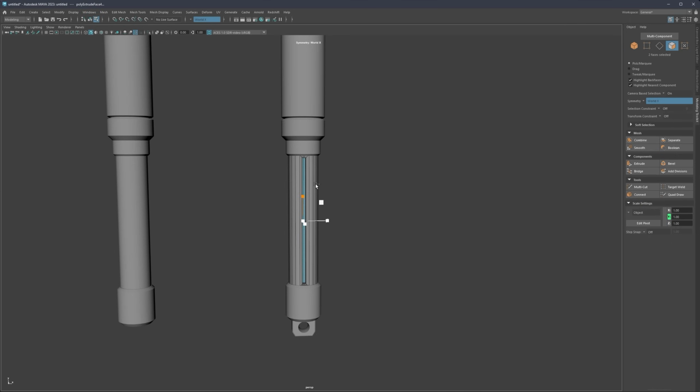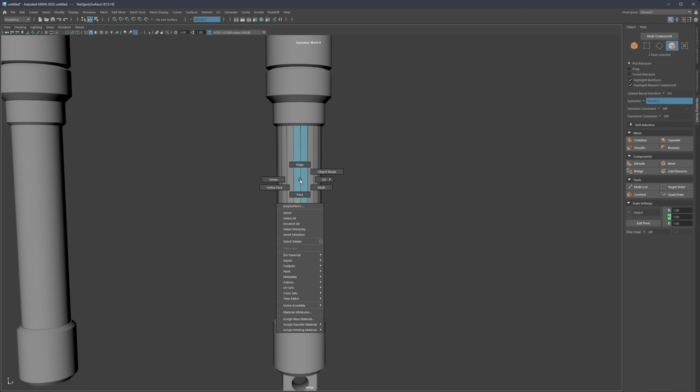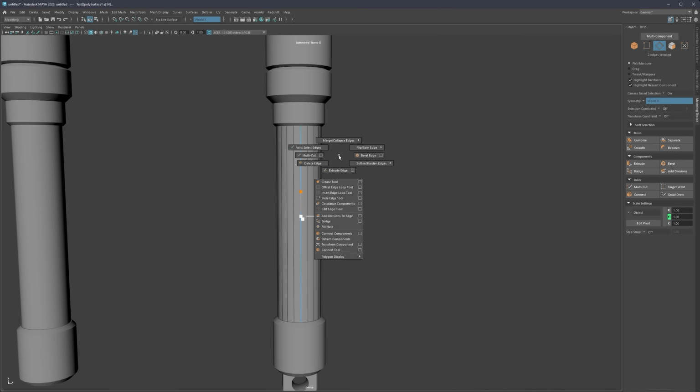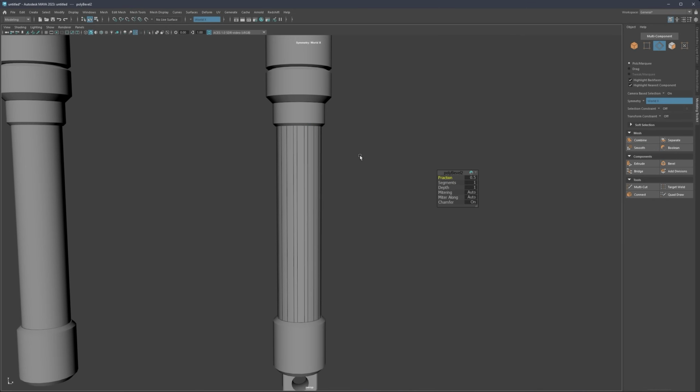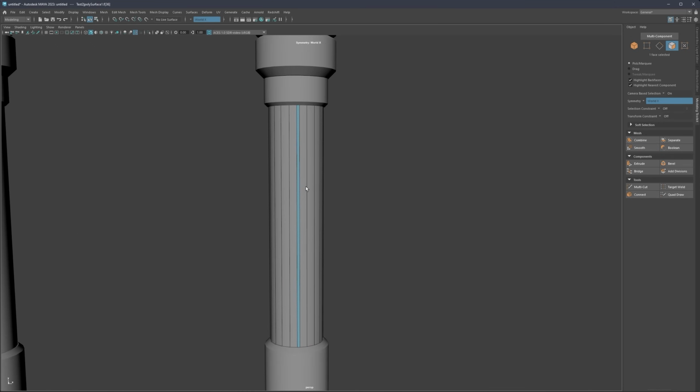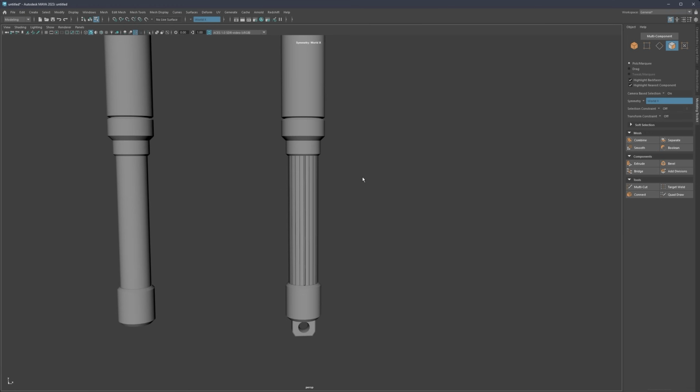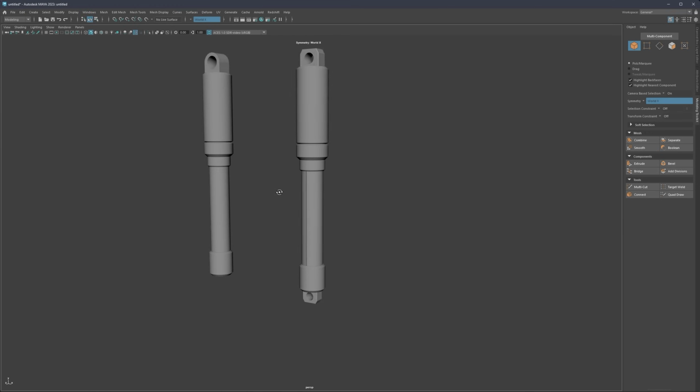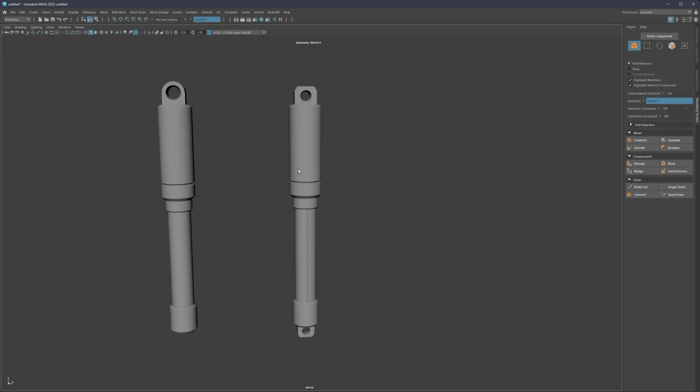Okay, maybe it's a bit too thick. Let's create it thinner. And instead I'm going to select the edge, and then let's bevel the edge. So let's go to Shift, right click, bevel edge, and let's say something like this, and then let's go to face mode, and then let's extrude this. So Shift, right click, extrude face, add slight thickness, and hit Q to confirm. And then let's go to object mode. Okay, so something like this, let's say, might work.